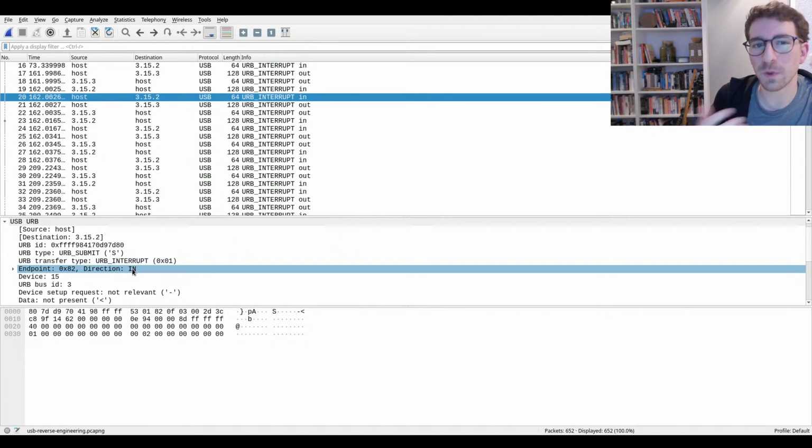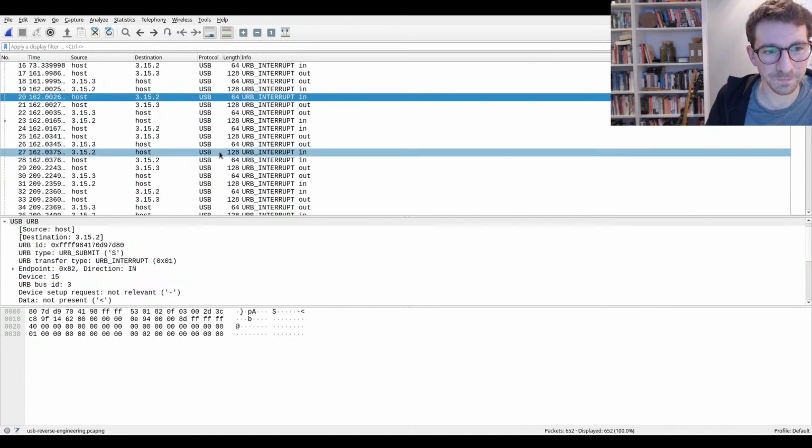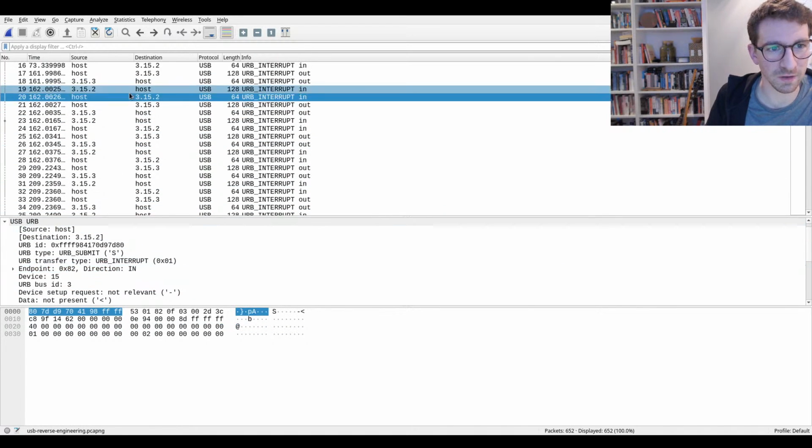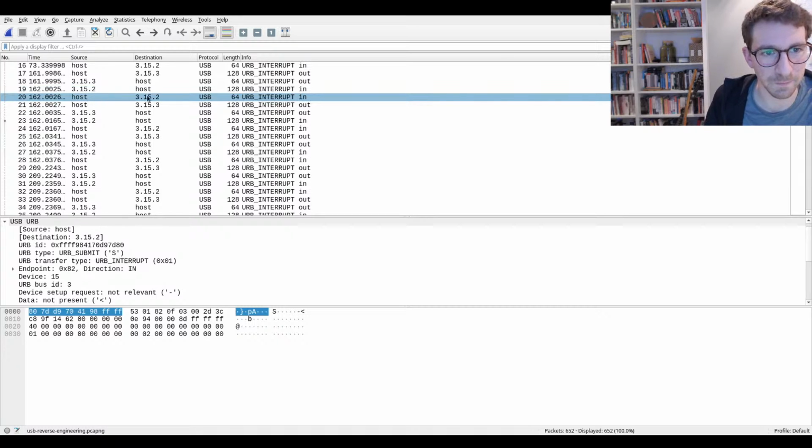This is when I eventually learned that everything is initiated by the host. When you talk in an in endpoint to the host, what you're saying is, send me some data. I'm triggering you to send me data. That's what's happening in this one here.